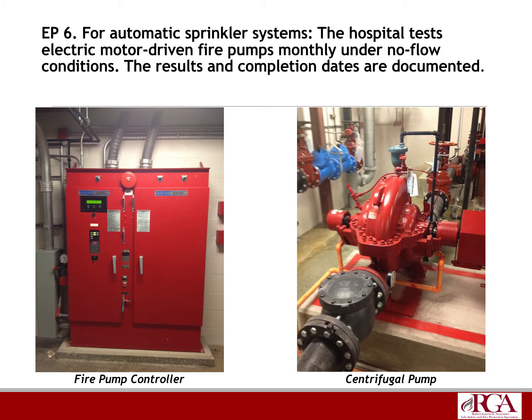EP6, for sprinkler systems, the hospital tests electric motor driven fire pumps monthly under no flow conditions. So this was a big change. As you all recall, this test has always been weekly for electric motor driven fire pumps. Now for diesel engine fire pumps, it is still a weekly test, and that you have to run it for 30 minutes. But for the majority of folks that have electric motor driven fire pumps, this test can now be performed monthly in lieu of weekly.